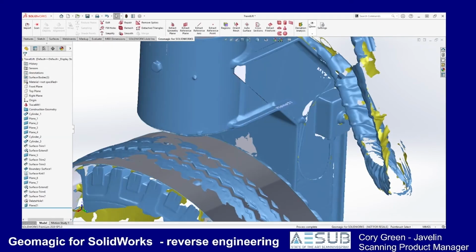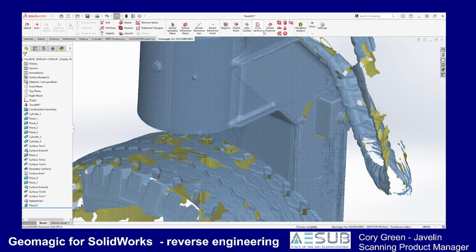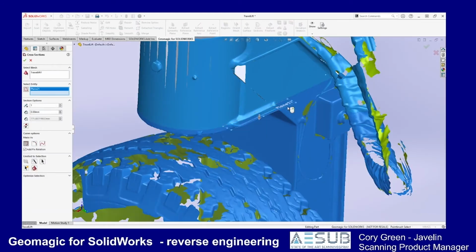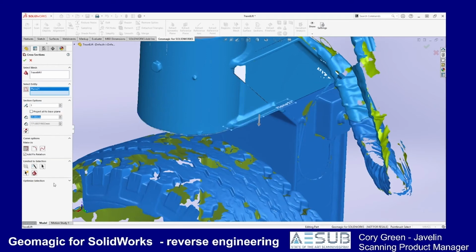We'll create it. The next thing we can do is extract a cross section. The cross section will be driven by this plane. In this case, we'd like to be offset from that plane slightly. Let's call that 20 millimeters, 20 millimeters up.